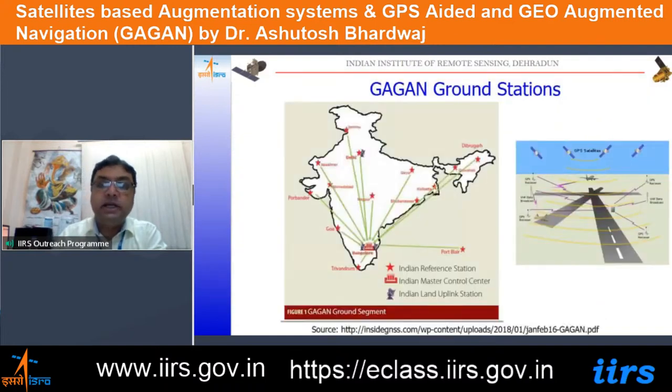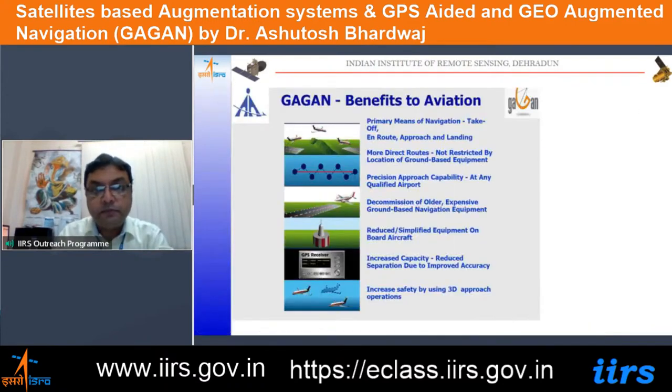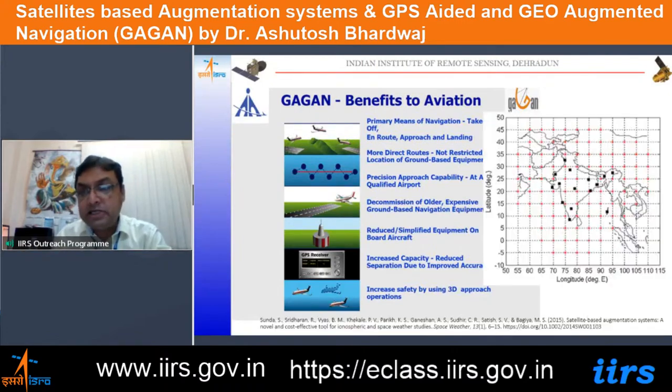Here we have to understand that GAGAN is a dependent system. The primary input for GAGAN comes from the Navstar GPS. Our reference station locations around India are known using the previous survey, so all these locations are already computed, and based on that, ionospheric correction parameters are also generated for the Indian region, and that further enables the correction in the Indian region.